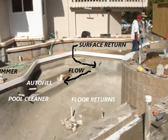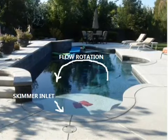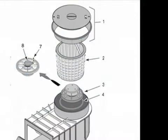In the placement of the suction skimmer, that component's positioning should correspond to an area somewhat removed from the turbulence being created by the returning water so that the suction's influence of the skimmer can capture floating debris and deposit it into the leaf basket located in the skimmer device.